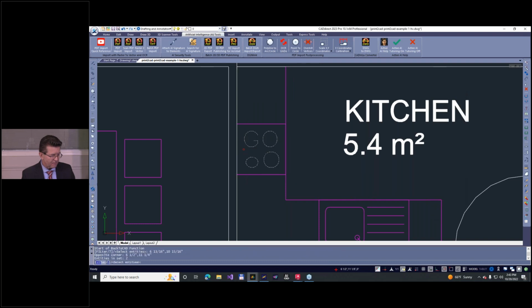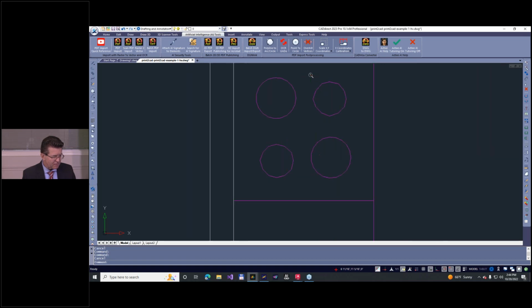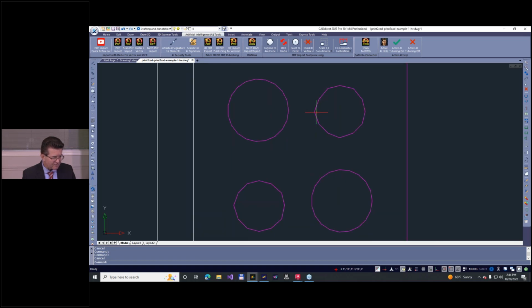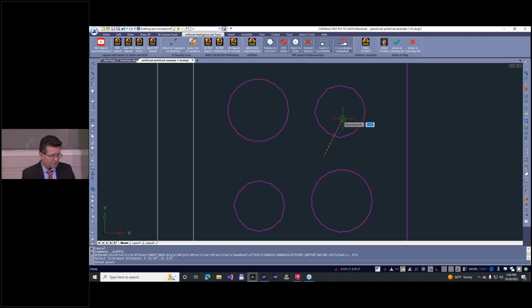here. Come. Okay. And now you see, this is a circle, but it's not a circle. Oh, but this is a circle. We were not able to recognize this as a circle because this was out of parameter. Can you see it? But no problem. In CAD Direct, pick huge tolerance, okay, and take this one and recognize as a circle.